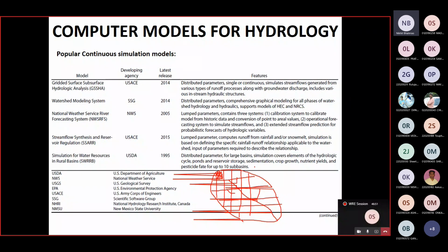Similarly, I'll be going to have the number of grids in this catchment area. For each and every grid, there will be individual calculation for the runoff. At the end, when we are going to have the simulation about the runoff data, as we are applying these various data sets for the smaller grids, the runoff which is calculated by that particular single grid will be the more accurate one.